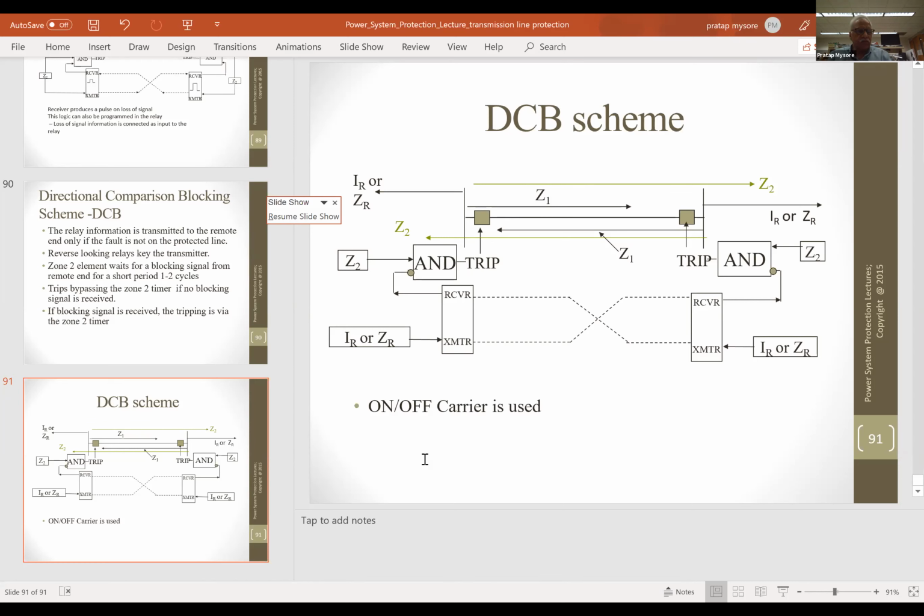So we went through that, and then we also looked at how the relays are designed. In static relays, they used phase comparators to look at the phase relationship between V and V minus IZ. IZ is actually the voltage that is developed across the setting that you put inside the relay. If these two are in phase, we block it. If they are 180 degrees out of phase, we allow it to trip. To develop the characteristics in the static relays, they used phase comparators, whereas in the microprocessor-based relays, they use products. You can look at the equations.